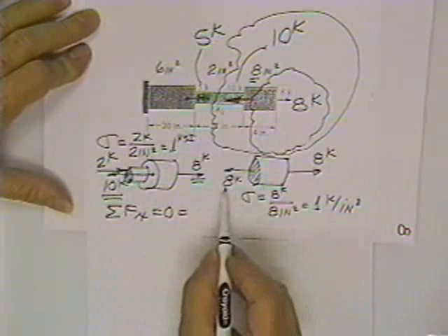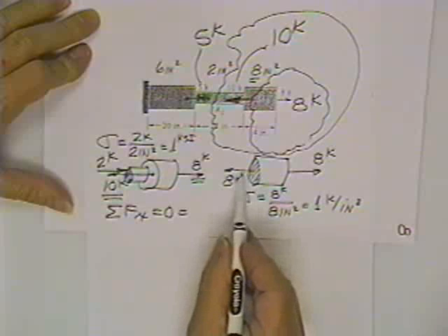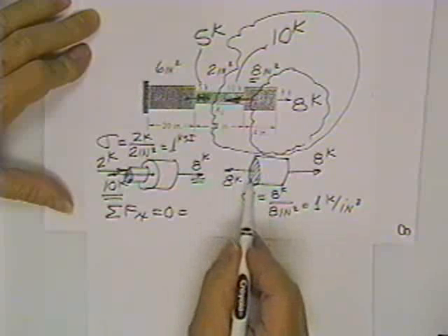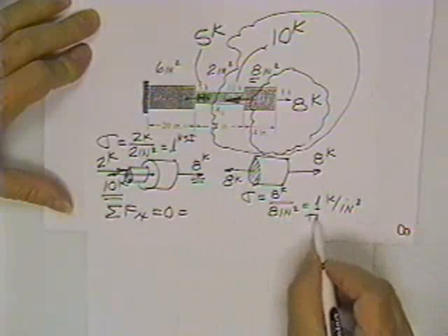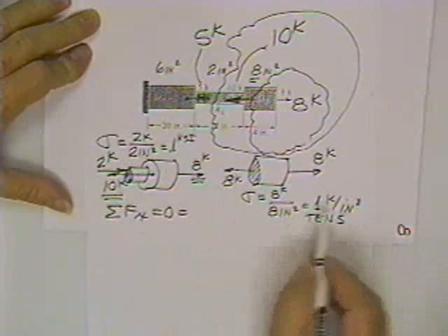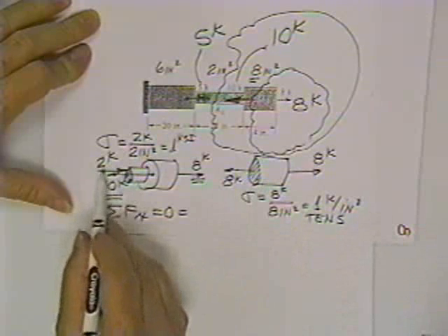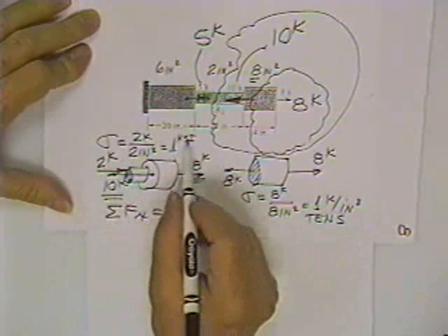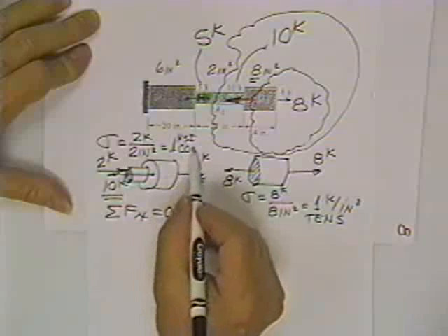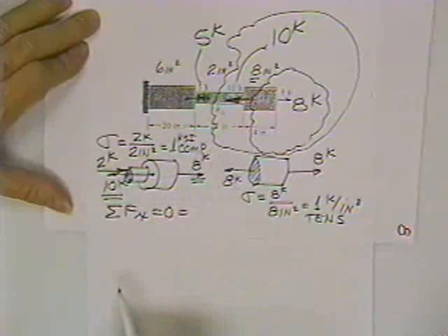There is a difference. You'll notice the 8 kip load has to stretch that area. It puts that area in tension. So this stress is a tensile stress. This 2 kip load has to press against that face, and therefore this 1 KSI is a compressive stress.